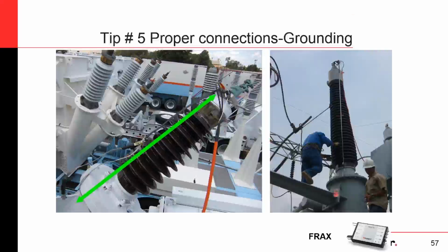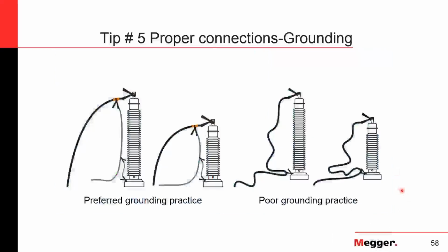Then one thing, and this is always mentioned, typical IEEE recommends doing your winding resistance test last, and also demagnetizing after you perform the winding resistance, because an actual magnetized transformer will change the response in those low range frequency, because you've magnetized that core and it's not going to behave the same since you're just putting a low voltage on there. So make sure that if you go through and you do your winding resistance, you demagnetize. But really, before performing winding resistance, you would want to perform this SFRA test, so it doesn't affect the results there.